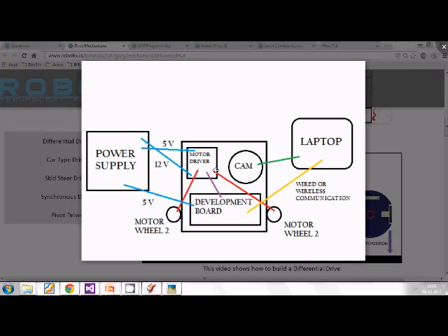Okay, sends signals to the motor driver, and the motor driver has something known as an IC or an integrated circuit, and that integrated circuit now gives voltage to the motors, voltage difference across the motors, I should say, to make it turn in a particular direction. We'll have to define through making this circuit and through our connections what kind of voltage from the IC for the motor driver leads to what kind of turning. That is something we can define, and that in turn powers the motors.